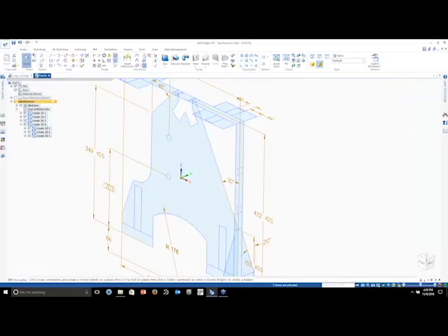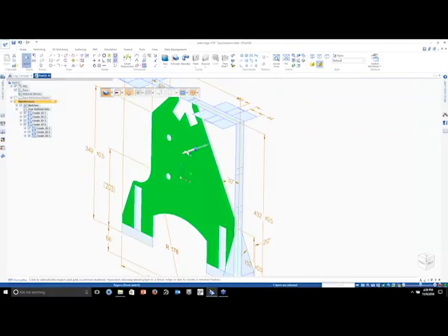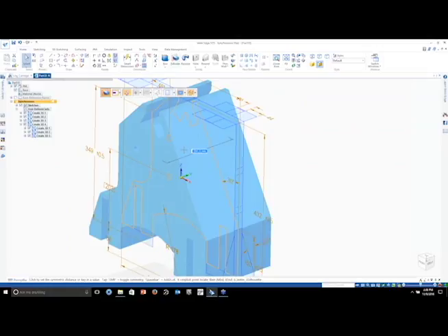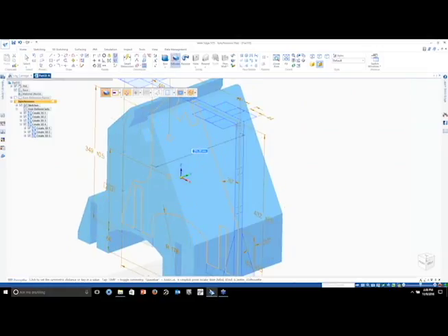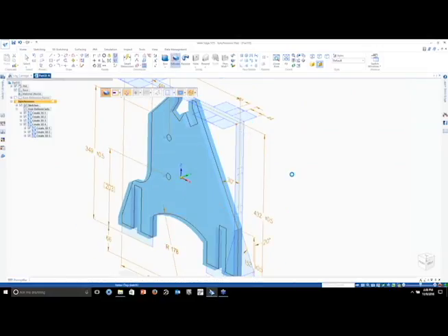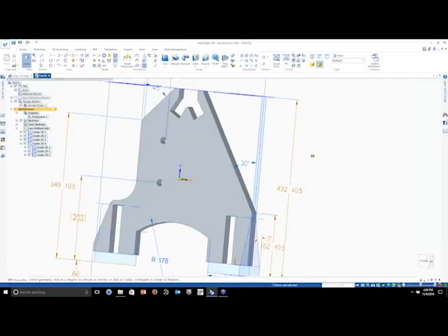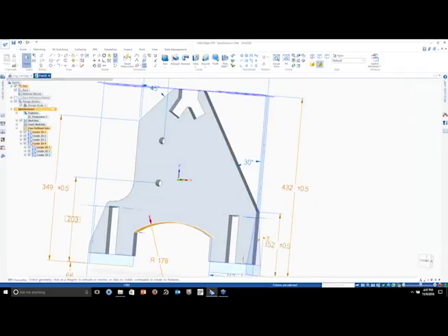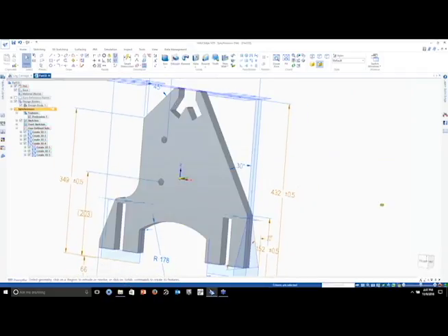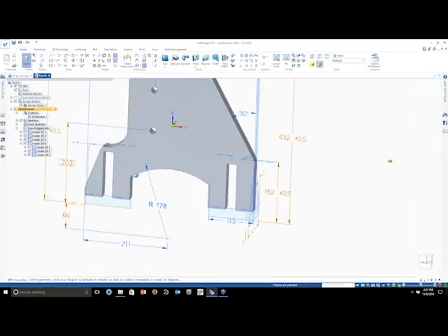So now I'm going to do the same thing here. I'm going to hit Shift and hold it on my keyboard. This allows me to go grab multiple regions. So when I'm done, I can let go of my Shift key, then just grab an arrow. Again, I want to go symmetric and just use another snap point. All right. We've got almost everything I need except the bosses here.